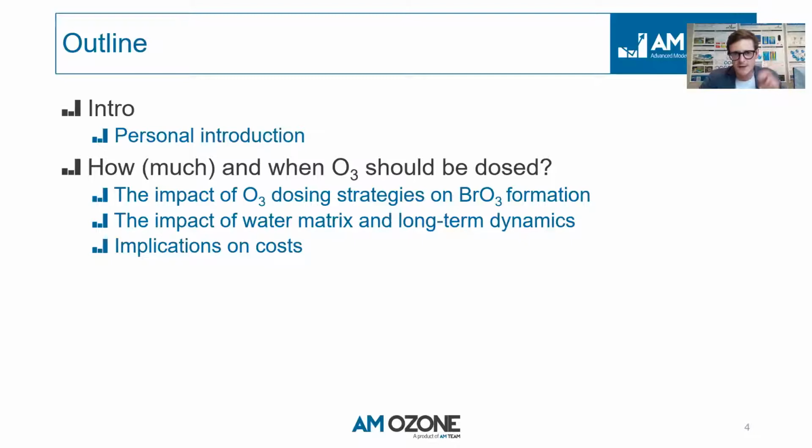We will start with a very short introduction. It's only 2 slides. Then you know who is talking, who we are. But then we will go into the content, and there's a lot to talk about. We will be talking about dosing strategies of ozone and also the impact of dosing strategies on bromate formation, because bromate is always an important topic in ozonation systems.